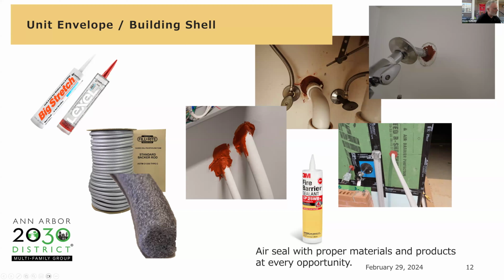The nice thing about this quick flash is it seals, as you can see, around the plumbing. There's probably a 1/2 inch gap all the way around that pipe, that now that quick flash is sealing tight. And then they're using the fire stop here to seal other electrical penetrations coming through.